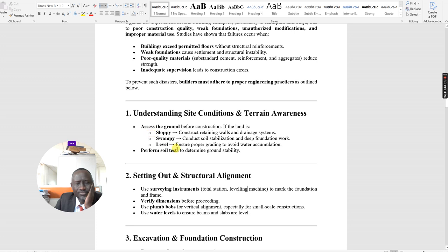So you have to be mindful of that. I think you have to assess the ground before construction. That is why it is important that investors engage the geotechnical team. They don't charge you too much, by the way. They ask for very little money. Once you have that prior investigation, you will understand, especially the depth of the soil upon which you are supposed to put the buildings. Once the building is set, excavation is done and construction commences, it is very difficult to begin rethinking your foundation. You have to proceed and go up. So you have to assess the ground before that.